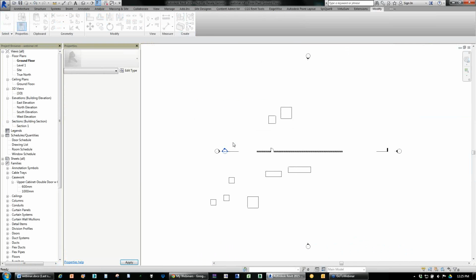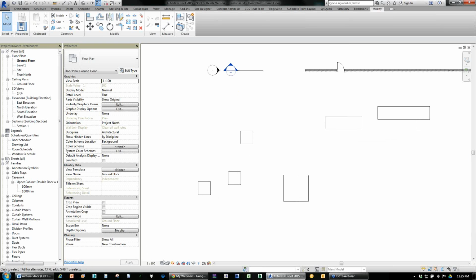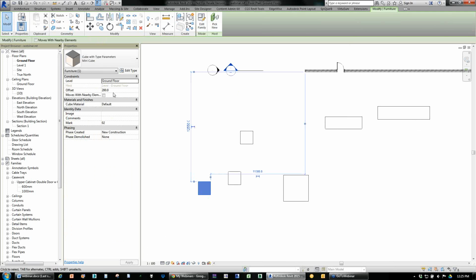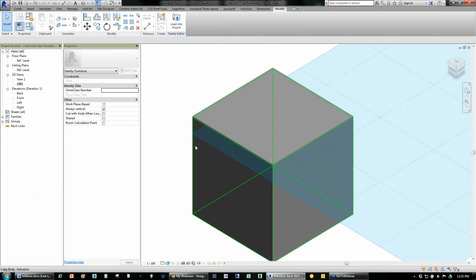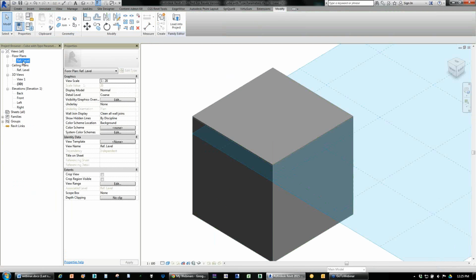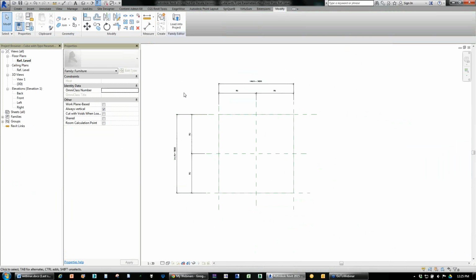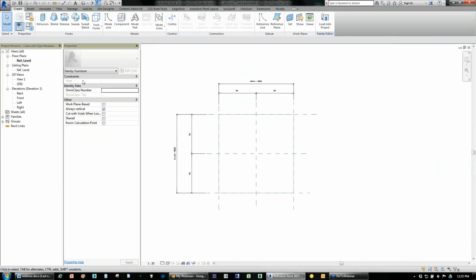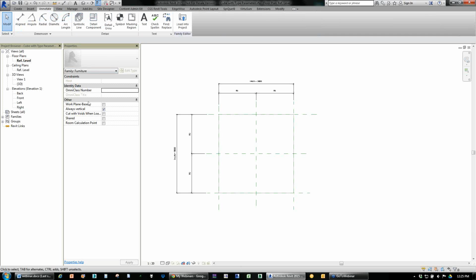Okay, that's fine. Let's load that in and just, I guess, see what that's done. Click on coarse, and there go my cubes. Still there, but just not visible. That's sort of half of the actual process. The other process is to then put in that simplified symbolic representation that I mentioned just before, and that's done here in Revit by things like a masking region.